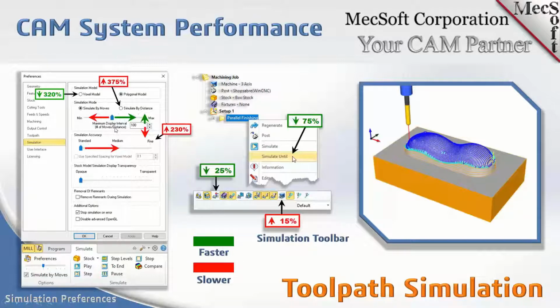You can control that by, if you simulate by moves, adjusting this value right here, the maximum display interval. The default display interval by moves is 100, so every 100 moves, the simulation on your screen is going to refresh.